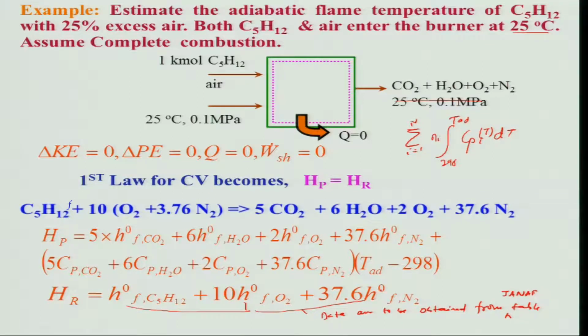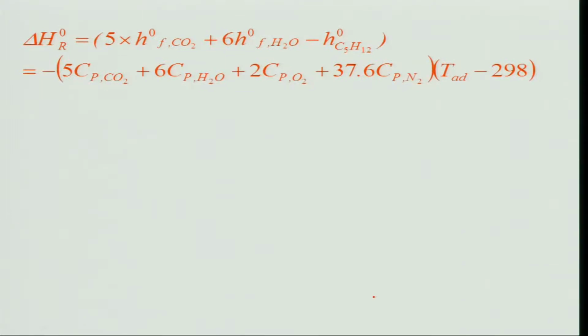So the heat of formation of individual species you can get very easily, and we will do that. Then from the first law we know H_P is equal to H_R, and we substitute H_P and H_R in that equation to see how to solve it. If you look at this portion for carbon dioxide and water, it is nothing but your heat of reaction, right. This is the heat of reaction.